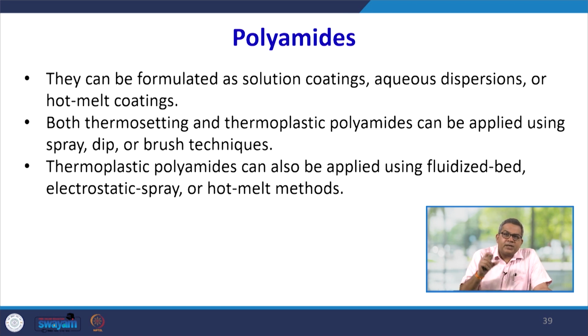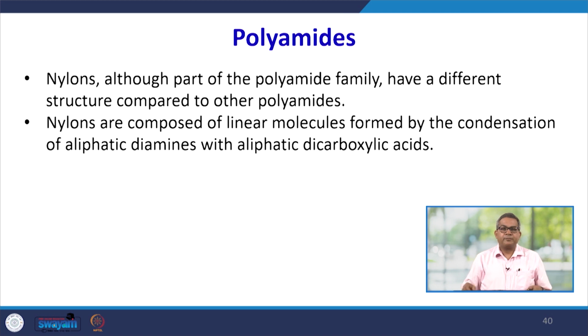Both thermosetting and thermoplastic polyamides can be applied using spray, dip, or brush techniques. Thermoplastic polyamides can also be applied using fluidized bed, electrostatic spray, or the hot melt method. Nylons, although part of the polyamide family, have a different structure compared to other polyamides, and they are composed of a linear molecule formed by the condensation of aliphatic diamines with aliphatic dicarboxylic acids.